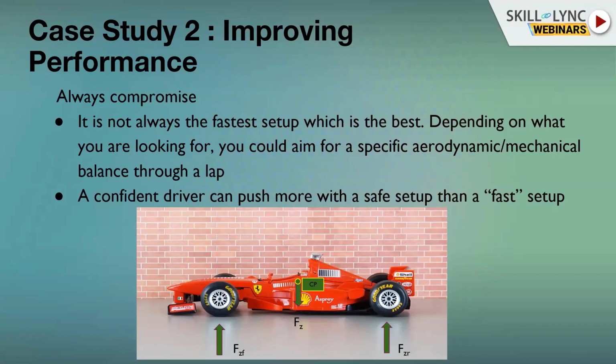If the driver is a kind of attacking driver, so he's brutal with the steering, brutal with the throttle, you always have to adapt your setup according to these parameters. And finally, a confident driver can push more with a safe setup.